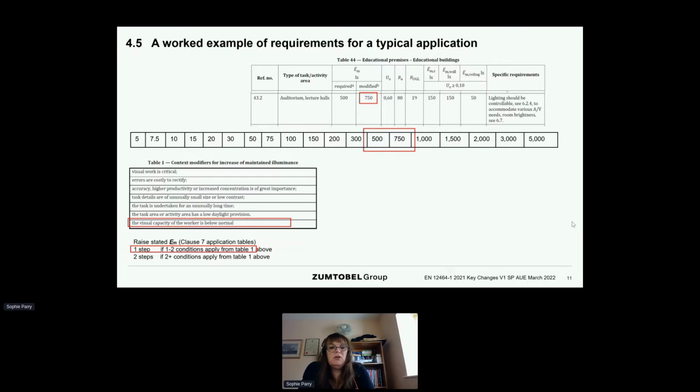And what the standard doesn't tell you is that 500 lux is only actually required at the task area where people do work. And if you're moving up to 750 lux, if you had, say, a big open plan administration office with 50 people working in it, would you really want to light the whole office to 750 lux because 2 people have visual acuity problems? Probably not. So for 48 people, it would be overlit, a bit glary, so they would suffer perhaps a little bit in terms of productivity, and also you'd be using more energy than you needed to be.